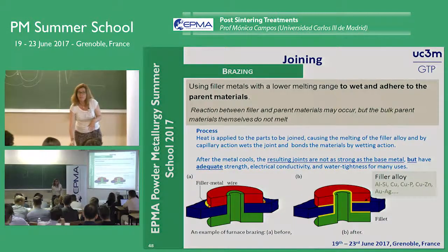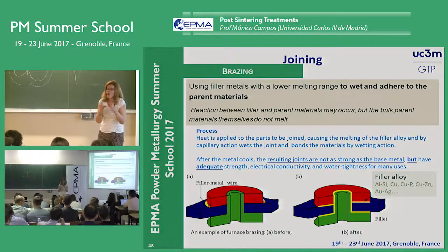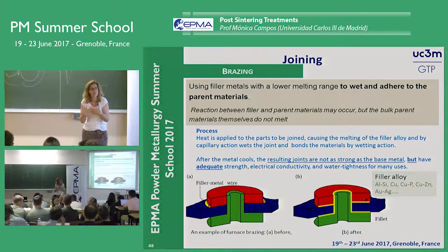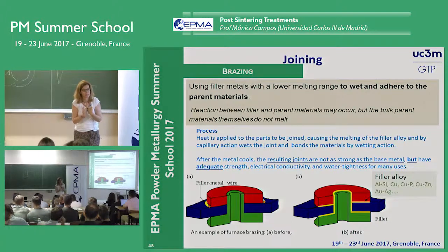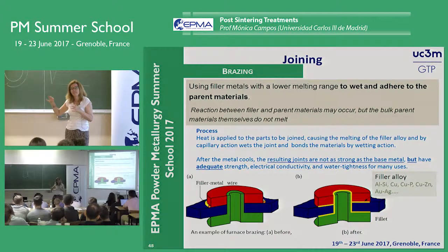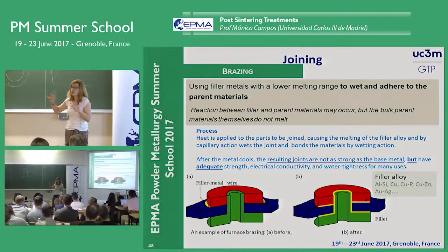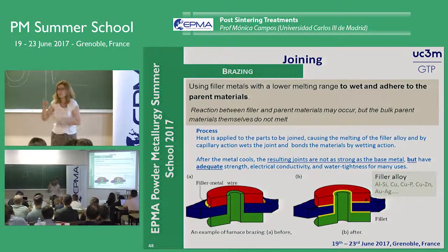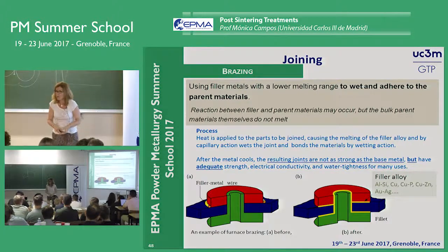What happens if you put too much, or if the dissolution with the component is very high? Then you are going to affect the final microstructure, or you are going to introduce a very big distortion of your component. Then it's so critical how this material melts and how this material is able to move into the pore skeleton of your component.